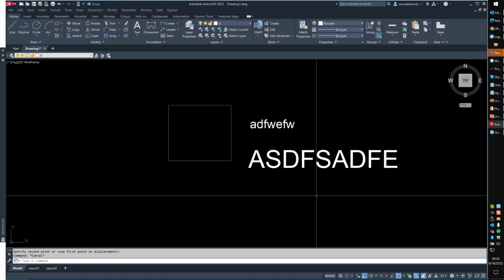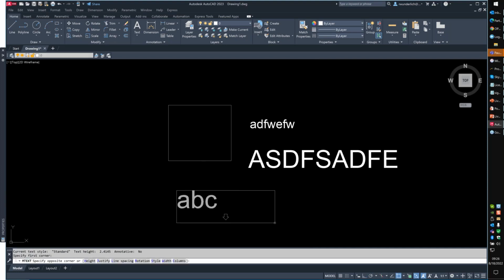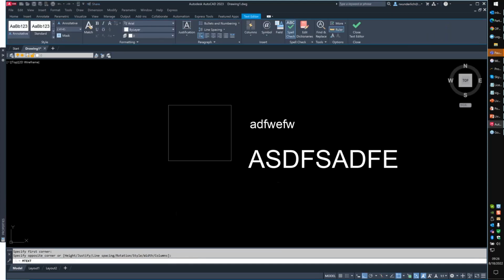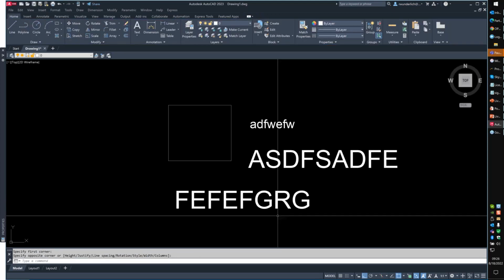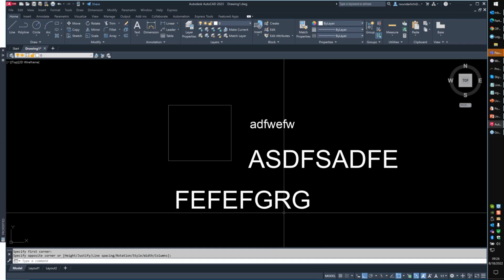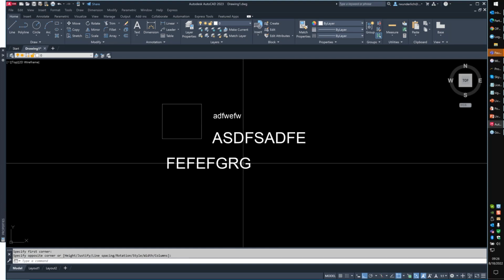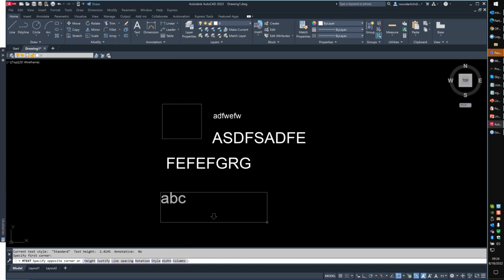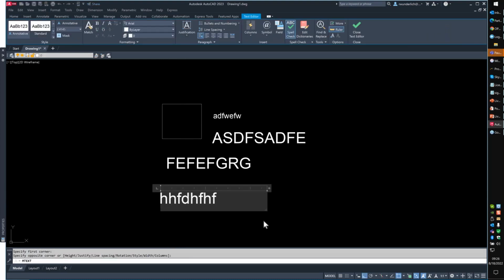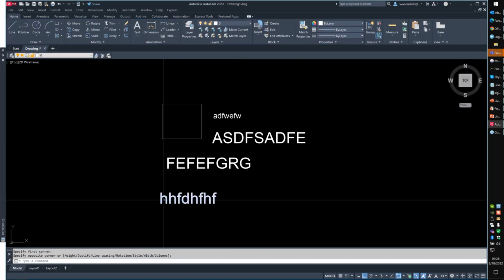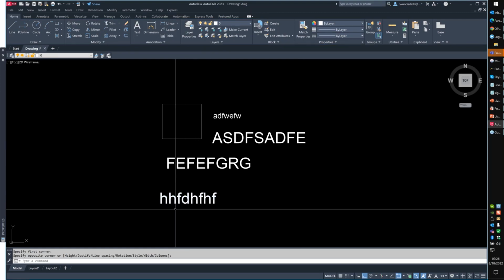And again, that's straight text or DTEXT. I can do the same thing in MText. Right, it's all caps. Yes, editing attributes in dialog boxes is still lowercase. That is absolutely right. Shift affects all caps. So if I'm in here and I do MText and I'm holding down my shift key, I click out. If I hold down my shift key, it will force lowercase. Otherwise, it's basically doing caps lock, but it's only doing caps lock in AutoCAD.